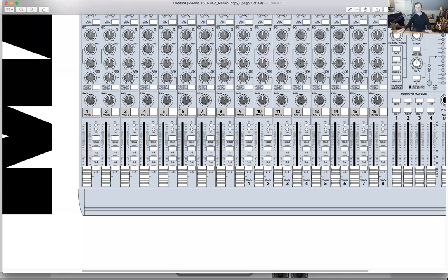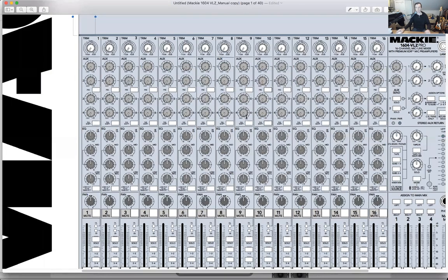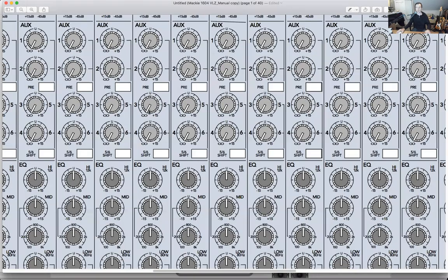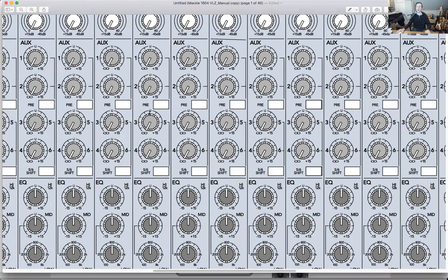I'm not going to go into the details of why you might do that, but I will jump up here to explain one other key concept of signal flow that is central to almost every audio system you'll work on, and that is auxiliary sends. So in addition to the 6 outputs in the main system, there on this console are 4 auxiliary sends. Actually, there's 6, but you can only access 4 at a time. And that's usually to save money or to save space on a physical console, an analog console.